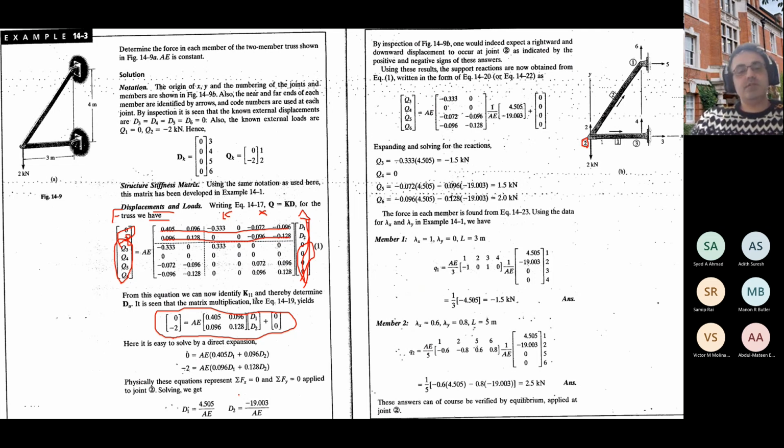And a very simple rule to do that is wherever you have the support displacements equal to 0, which means in this case rows 3, 4, 5, 6: if I have this 0 here in the third degree of freedom, just go and delete the row number 3 and column number 3.